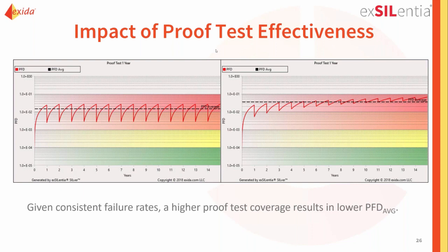So I can go to a transmitter manufacturer and ask them for their safety manual, and it will tell you a proof test with a proof test coverage. And what you will typically see is proof test coverage in the 90+% for transmitters. Usually there are tests that are relatively easy to perform by you as an end user that can get very high coverage factors. But if we look at the final elements, it's a little bit different.